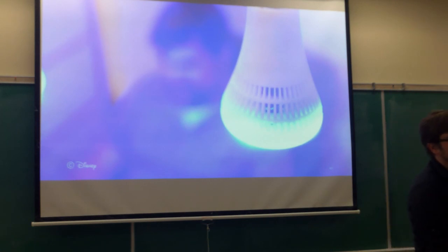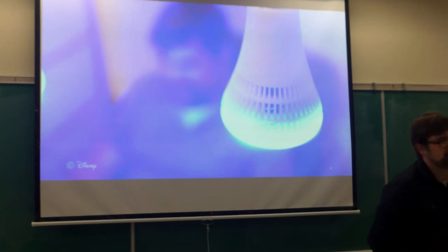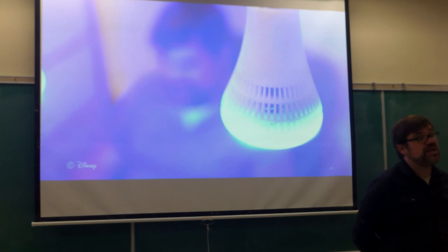For the example of the thermostat, basically the linear movement of the RFID determines how far away the RFID is? Well, no, in that case, we actually cut the tag. Inside of a mechanical thermostat, there's a mechanical part that moves. So when you move that metal away from the RFID antenna, the performance of it gets worse. What resolution can you detect? Oh, that's just binary. I would imagine it's not that good. We just used it for a binary classification between whether the heating is on or off. Okay. I wouldn't trust that you could use it to do better than that.